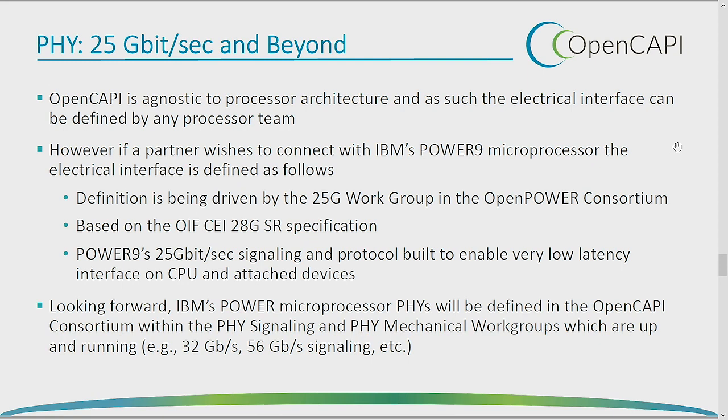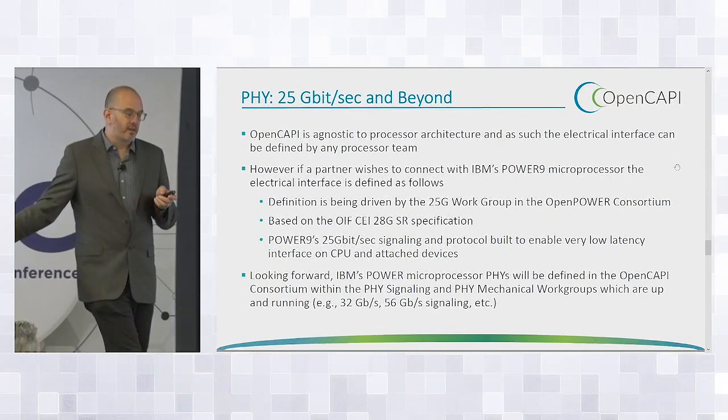And this is an interesting thing in that the silicon area is mostly dedicated to the SerDes signaling. The actual block that decodes and translates the protocol is pretty tiny. So far we've been successful with having 3 technologies on this protocol, and it's really quite tenable. It's not a significant tax on our processor chip.